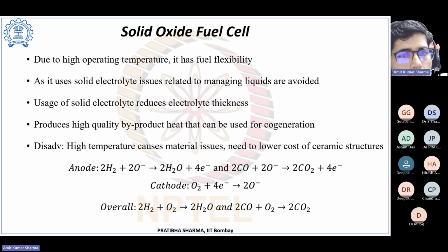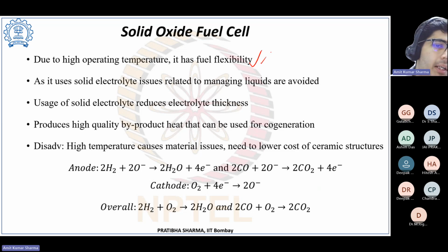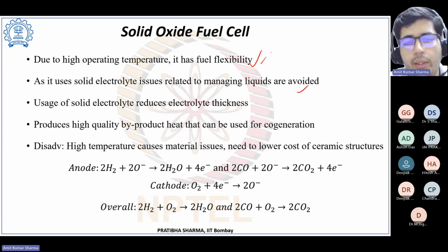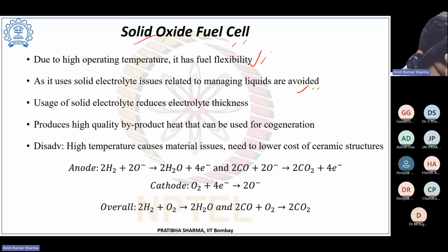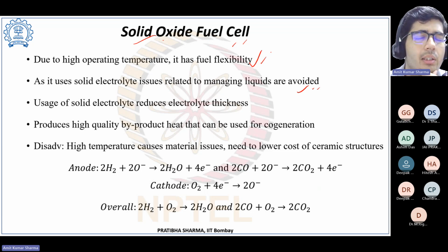Now SOFC, solid oxide fuel cell. Due to high operating temperature, it has fuel flexibility. You can reform the fuel inside it. It uses a solid electrolyte, so issues related to managing liquid are avoided. So in this also, the electrolyte is solid as compared to other fuel cells, those which are using liquid electrolyte.